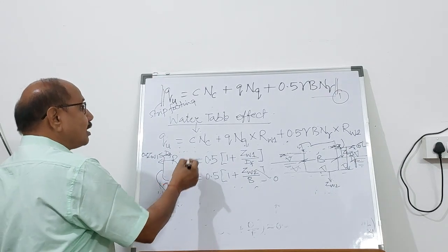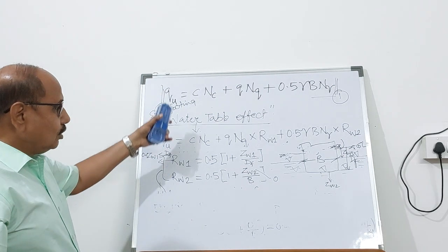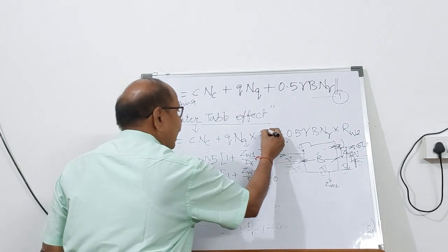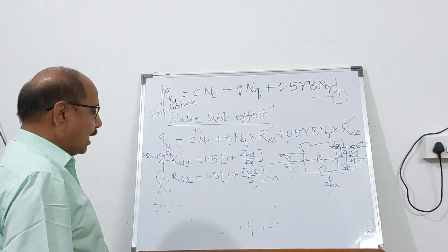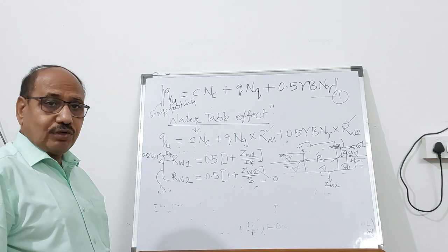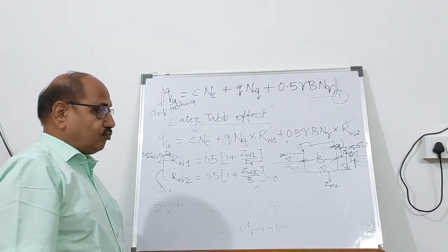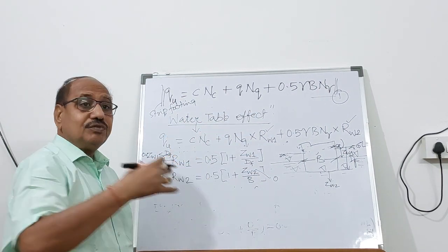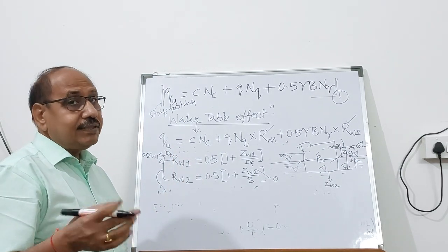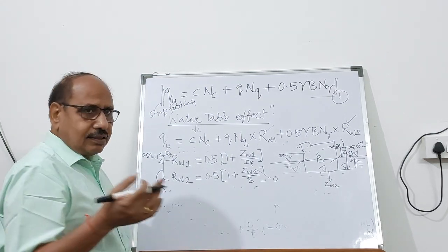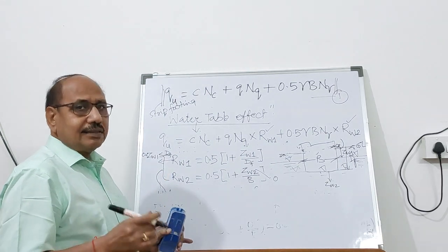So these two equations are very, very important, and it is the water table effect that you will have to multiply and calculate for various conditions. I will solve some examples and let you know how these things can be calculated. If you solve more problems over this, you will be able to learn the effect of water table and shape effects. If it is not general shear but local shear failure, how to use all those things can be explained in the next video, so that you learn all your theoretical concepts in a much better way. Thank you very much.